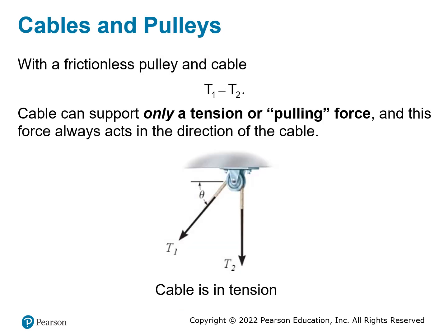The second common kind of force that we want to talk about is the cable and the pulleys. We told you before already, when you look at a cable, it can only provide a tension force. The tension force is always pulling, which means the force is always away from the point that you are looking at.